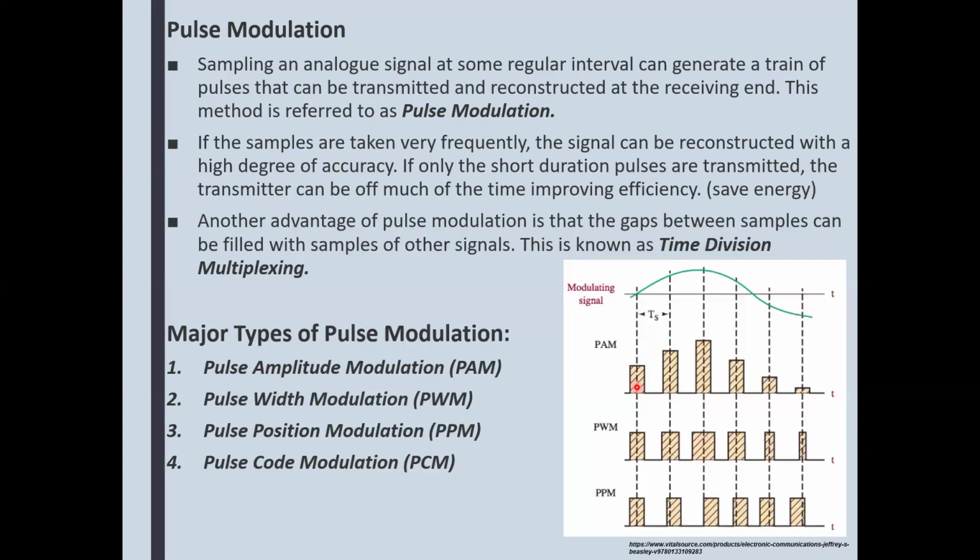So there's going to be a signal that says, okay, start listening now, and then listen at those intervals of time, so you're going to be able to recreate. So the baud rate of the sender has to be the same as the baud rate of the receiver. That's how things are being synchronized. Where does time division come through here? Time division multiplexing.